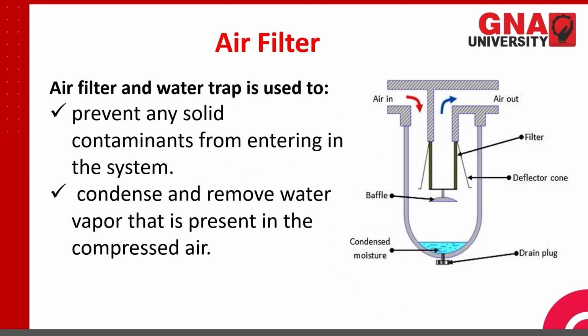Then condense and remove the water vapor that is present in the compressed air. That is done primarily in the air dryers, but if some contaminants are left, then they can be separated in the filter stage also.